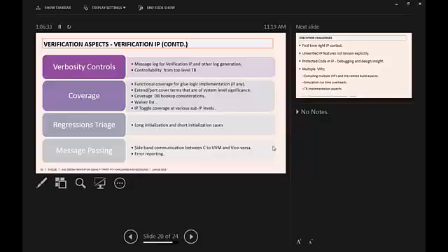Right, yeah, that is not, but I don't want to throw away whatever I already developed. Yeah, that is what. So on the controller side, you may not be able to use it, right? Because the SoC is sitting there on the other side, not the VIP. But on this side, it is used as a responder. On the controller side, your UVM is driving the traffic, but it's going to your AXI bus and going to some endpoint. Yeah, correct, on the IP level. On the controller side, what is doing that is a very intelligent UVM component.